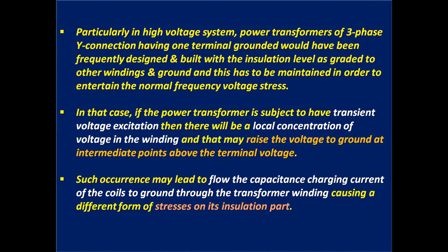Particularly in high voltage systems, power transformers of three-phase star-connected transformers having one terminal grounded are frequently designed and built with the insulation level graded relative to other windings and ground, and this has to be maintained in order to withstand the normal frequency voltage stress.